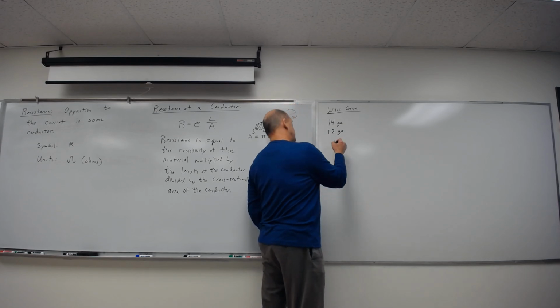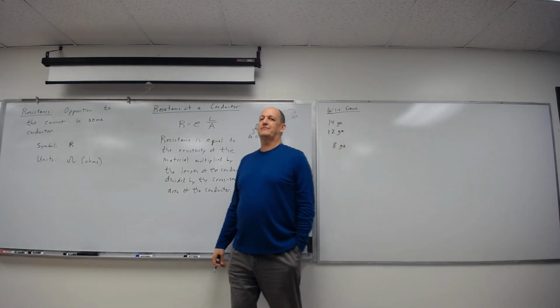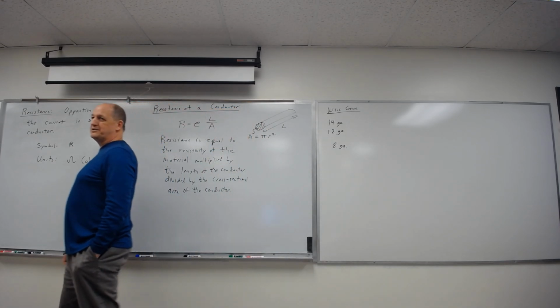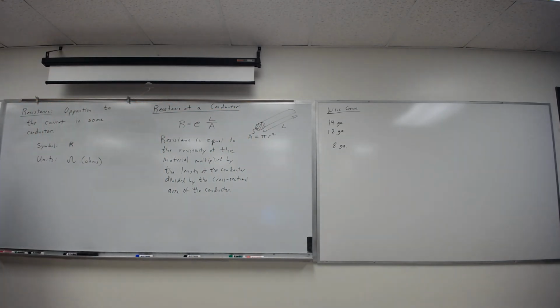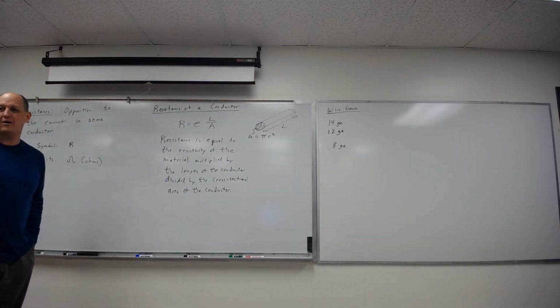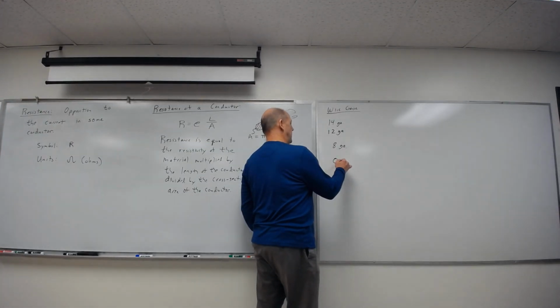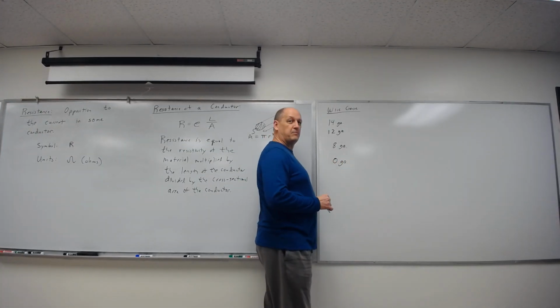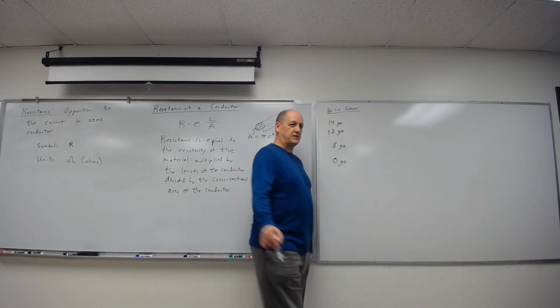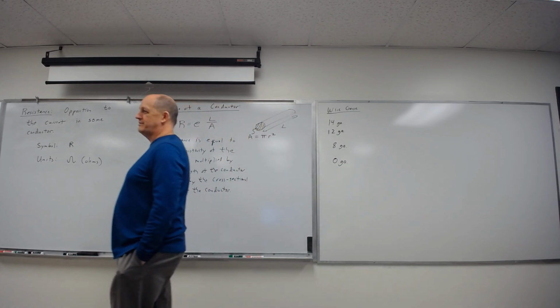If you go up to something like 8 gauge, you're not going to bend that without grabbing onto it with pliers, and maybe needing 2 people. But you can do it, because that's how you do industrial, high power wiring. You go all the way down to 0 gauge for high power. By the way, I've run out of numbers. Anybody know if I need something bigger than 0 gauge, what do I do?